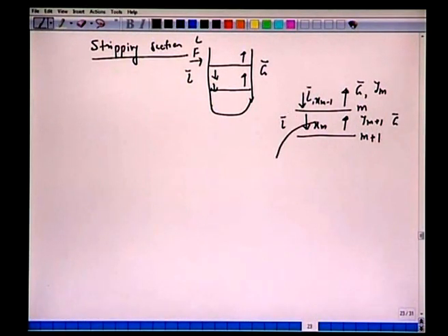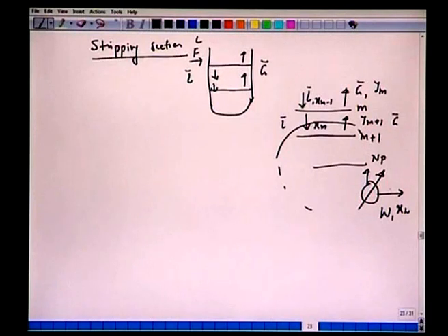If you take this envelope with xm and ym plus 1 along with the reboiler, where the stream has this molar flow rate, say W, and we have xW. Alright, so this goes to the last plate, which is NP. Now since we have this reboiler, this is yNP plus 1. These two streams are in equilibrium, xW with yNP plus 1. Now if we make the species balance and the total balance, L bar equals G bar plus W. So this is the envelope which we have made around this.